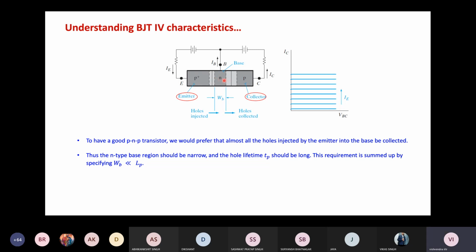Actually, we generally want the base region to be thin, but we do not want it to be zero, because in that case the majority carrier current becomes zero, or very small, in the base. So the control of the base on the total current is taken away if punch-through happens. Although that is desirable in some optical applications or specific cases, it is not always. Now, is there any question?